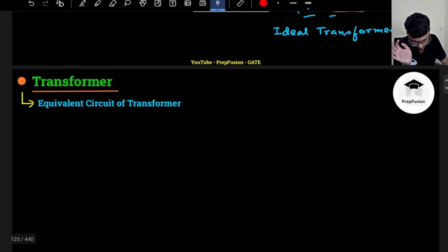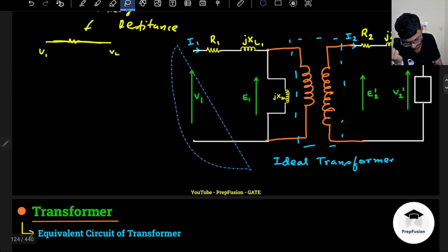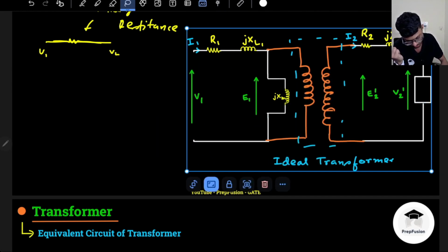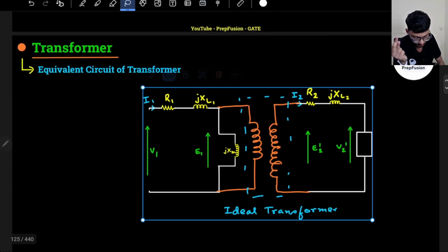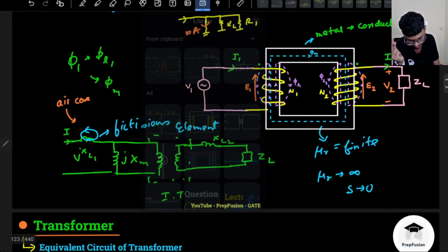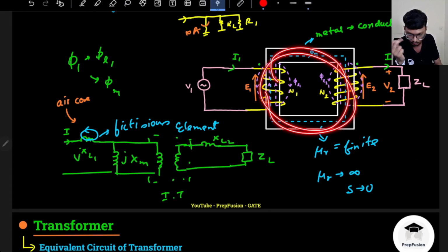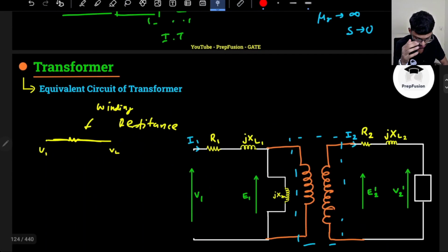Okay, so actually this component will have another component added. So there will be a resistance in parallel with this, because that current will not flow through the secondary. That current will not go and link the secondary. That current will just flow in this loop. So there is a division between this winding current and this current. We will discuss that.